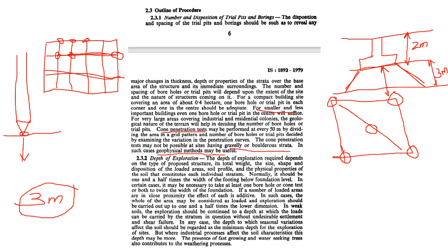Just imagine, that is the depth up to which the effect of loads will be existing in the subsoil below the footing. Okay, so then you have to make sure that this point where the loads are finally going to rest also has sufficient bearing capacity. Okay, so for assessing that only, depth of exploration will give you certain depth of boring recommendations based on the type of foundation. How it is relevant is what I am explaining.